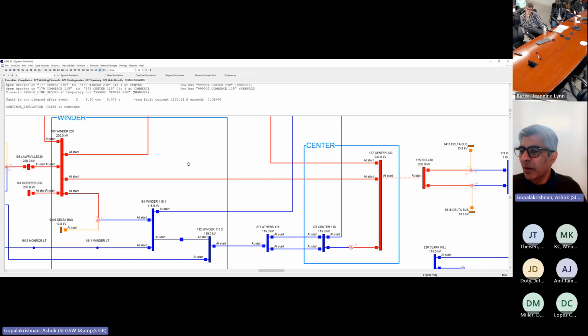Those are what we call the N-1 type of contingencies, where you remove one object, usually at the line terminals, one at a time. Other than that, you can also define your own contingencies, where if you have some critical generation in the system or nearby that you want to outage, you can consider that as added contingencies. And all of this can be stored in configuration files and recalled every time you repeat. But common practice is to look at the immediate line terminals and outage the sources of fault current that are immediately connected there.